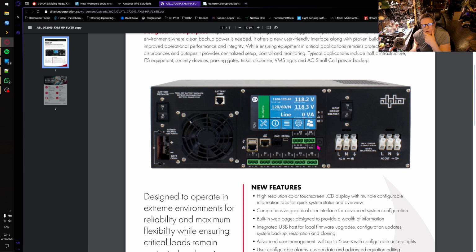And so you can actually have wake-ups. Now, the other thing you've got here is you've got relays, okay? So you can actually tie the relays here into a trigger port on your server that will bring the server up when mains is restored, okay? There's all sorts of different ways, different mechanisms you can use. You can even have the lights out interface with this as well, so that when the power comes back on, mains is restored, it will automatically push the power button for you.